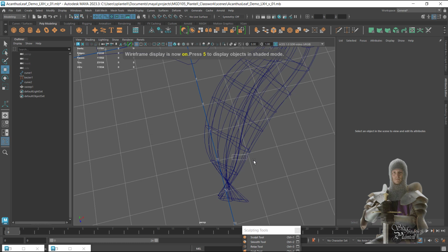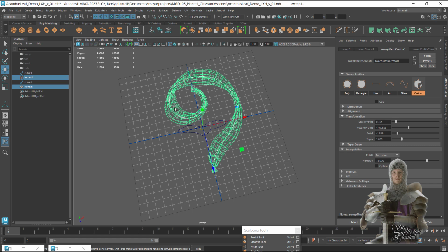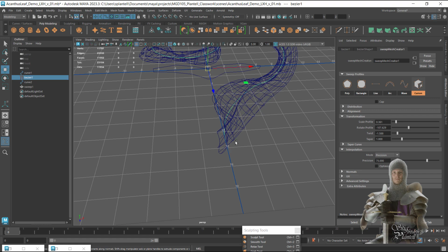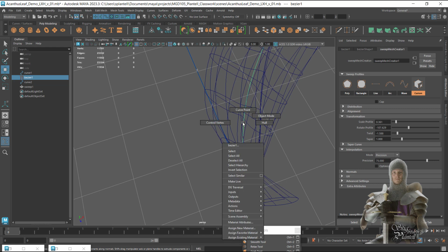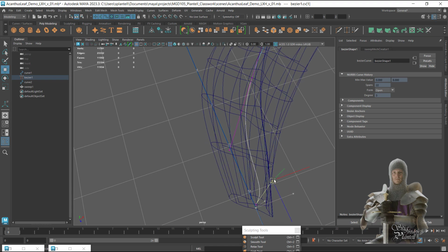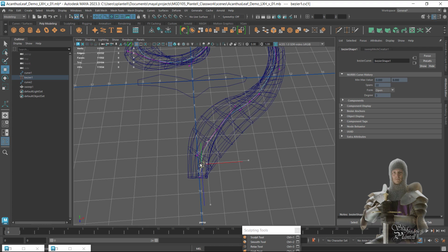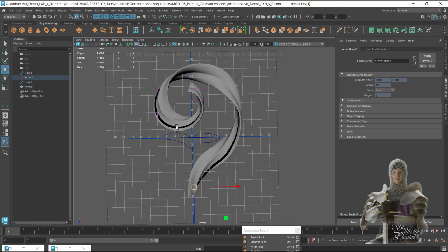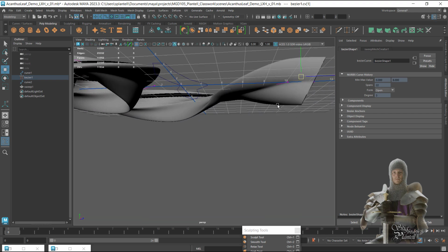I am hoping to go in and modify this curve. So I'm selecting everything that has to do with this form. And I'm going to shift deselect by dragging on the mesh to get to the curve here. I'm going to go to Control Verts. I'm going to take this tangent at the end and straighten it out so it's not such a mess. You can roll that until it's a little less tangled. Now, that's already looking rather beautiful. It is cutting through itself a bit though.